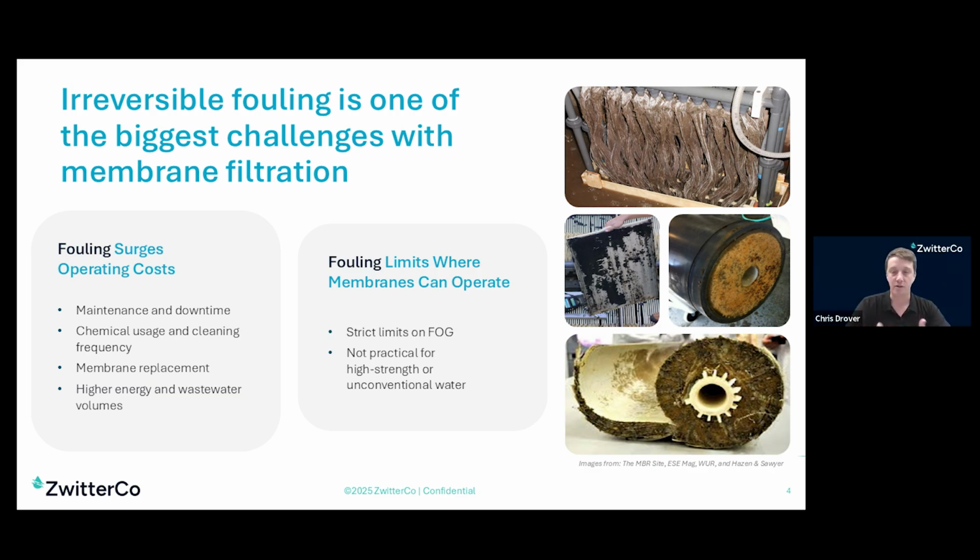And so one might ask, what is organic fouling? It's essentially what you see in the pictures on the screen. This is a process by which organic material that's dissolved or suspended in wastewater will reduce the performance of a filtration membrane. And in many cases, this can be irreversible. We see organic fouling as one of the largest limiting factors in the broader adoption of membranes in applications like water reuse and wastewater treatment, and even some food and processing industries. Fouling increases costs and limits the different use cases where membranes can be deployed without extensive upstream pretreatment to reduce the organic burden.